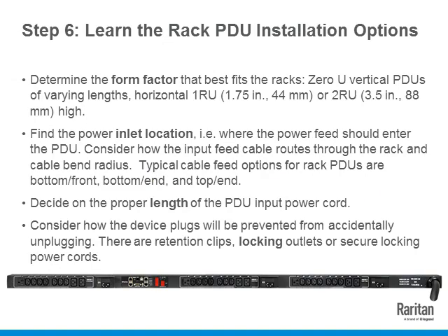Step 6 would be to learn the PDU or the rack power strips installation options. You have various form factors to deal with, whether it's a 0U that goes in the back of the rack and does not occupy any rack U spaces, or these 1U, 2U devices that go into network racks where you have plenty of RU spaces available.